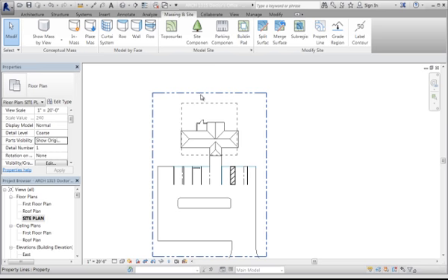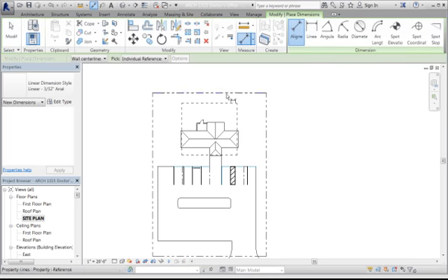It would all just be zeros. But you can make something up, but then the length has to be correct. If you want to make something up, then you could put the numbers in there, but I want it to look like site numbers. So you can say south 53 degrees, 28 minutes, 0 seconds east for 116, whatever the decimal is. And then you do the same thing over here. That dimension establishes how big your site is. Then from that, you would dimension your setbacks.